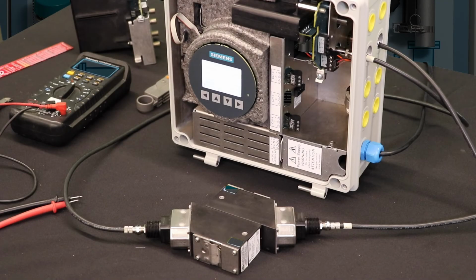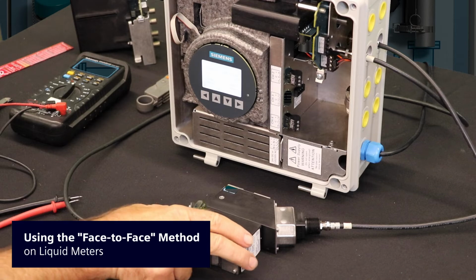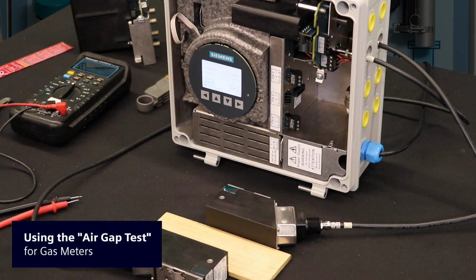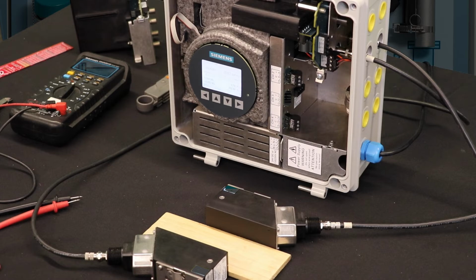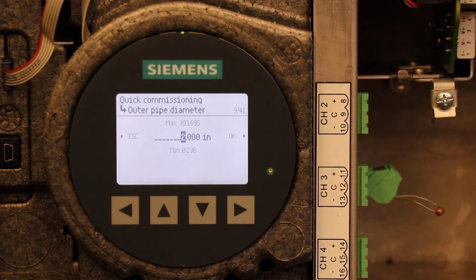We have another way to determine if the equipment is working or not, and that is either the face-to-face test for liquid or the air gap test for gas. Now, we have to program the meter appropriately for this to work. If you're using the face-to-face method rather than the pipe wall method, you can use it with steel or plastic or ductile iron or any pipe material, because this test doesn't involve the pipe at all.